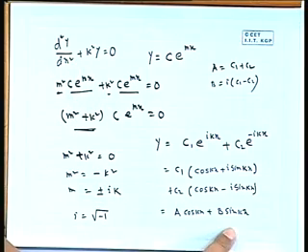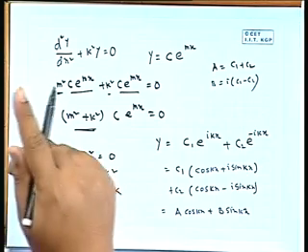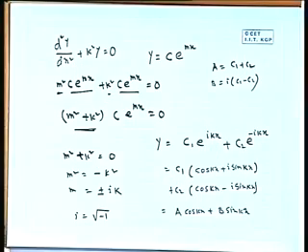So the total expression is in a general form, say A cos kx plus B sin kx. Now there are two constant quantities, and these two constant quantities we have to find out from the boundary condition. So in deflection of beam, more or less you did the same thing. You have taken d2y by dx square is some moment, integrated, got some constant, substituted some boundary condition, and the constant you obtain. Now here what are the boundary conditions?